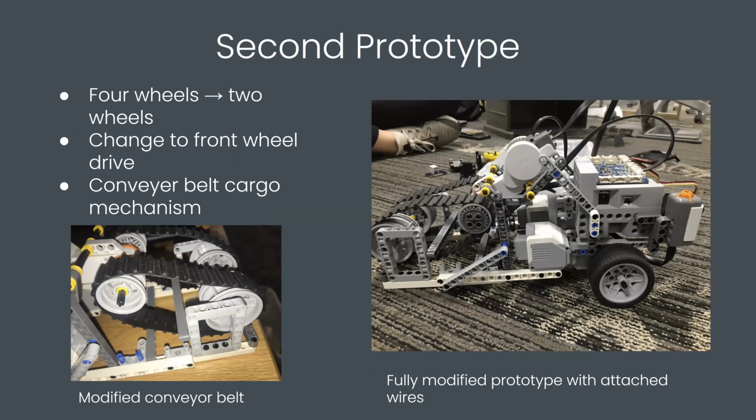The change from 4 wheels to only 2 wheels in the front was made due to friction between the wheels and the ground. Because of this friction, turning using different positive and negative speeds for the left and right wheels was virtually impossible. By using 2 wheels instead and having a more sled-like base, the macro could spin in place, reducing the turning radius to practically 0. The change from rear-wheel drive to front-wheel drive was necessitated by the fact that the sled at the front would be unable to go over the obstacles.